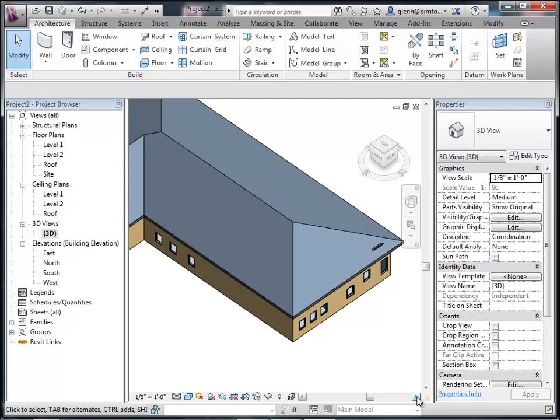You want to create some workspaces for the researchers, and they want little desks and chairs. They don't need the executive roll-top desk or the credenza. They need a little table and a chair to sit at with a little laptop computer. Very modest, about 40 to 50 square feet for each desk. They want to have some lab bench. Picture an 8-foot-long bench, 3 feet tall, that has a little sink in it. Someplace where you can put some instrumentation, just have some things set up to work on.